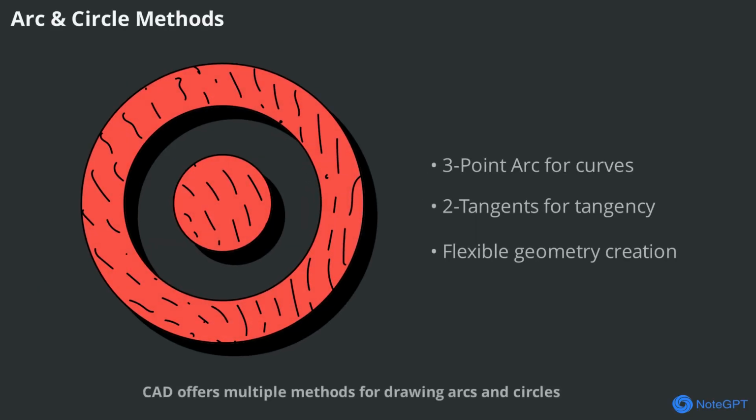CAD offers multiple methods for drawing arcs and circles. The three-point arc defines a curve passing through 3 points, useful when center and radius are unknown. The two tangents and a point method creates a circle tangent to 2 objects and passing through a specified point.